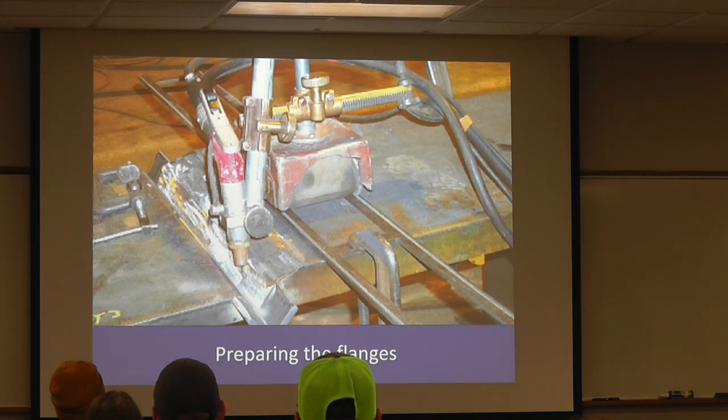And so we have, these are called runout tabs. They're simply there to let that transition happen outside of the girder while we turn back around to make a multi-pass weld. Because this is probably, I'm guessing on thickness, a 7 or 8 pass weld. So these will get ground up and removed by the fabricator once the weld's been tested.